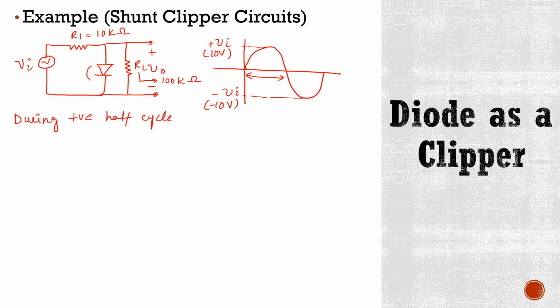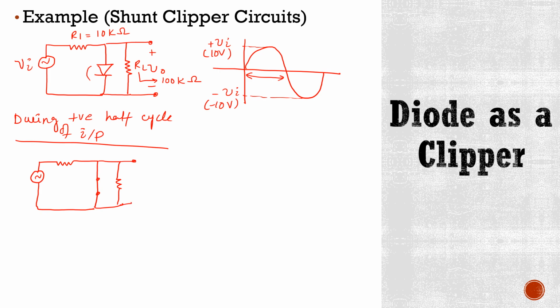Now in this case this circuit will look like this, where this diode is short and here we have a resistor. We know that this is positive, negative V0. Here we have VD. This is positive, this is negative, and now this terminal is positive, this is negative, this is Vi, and this is R1, this is RL. Now just look at this loop.